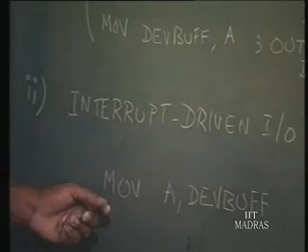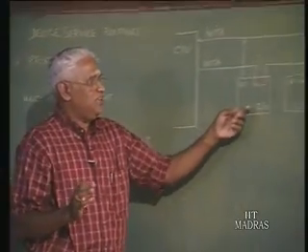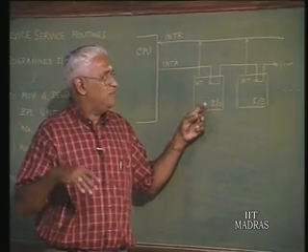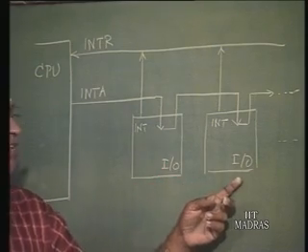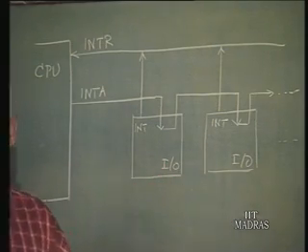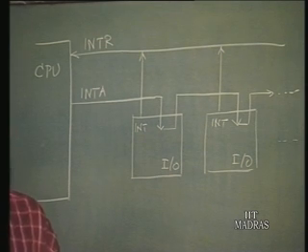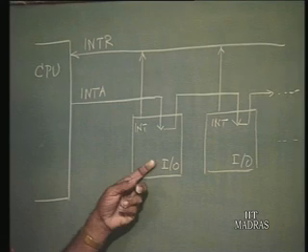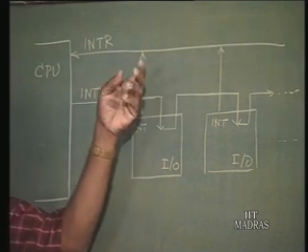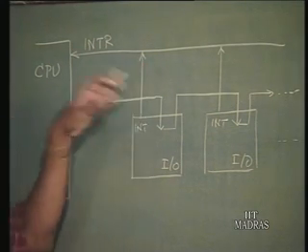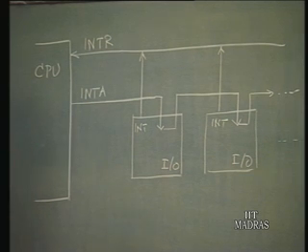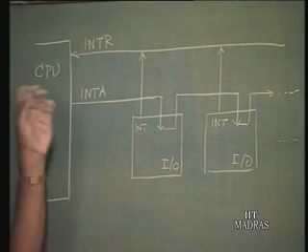Okay. So, let us say for the first device, the interrupt service program is starting from location 100. For the second device, it starts from location 200 and so on. For the third device from location 300. Essentially, this device must say my service program starts from location 100. So, it has to send a code which the CPU will make use of and link to start address 100.